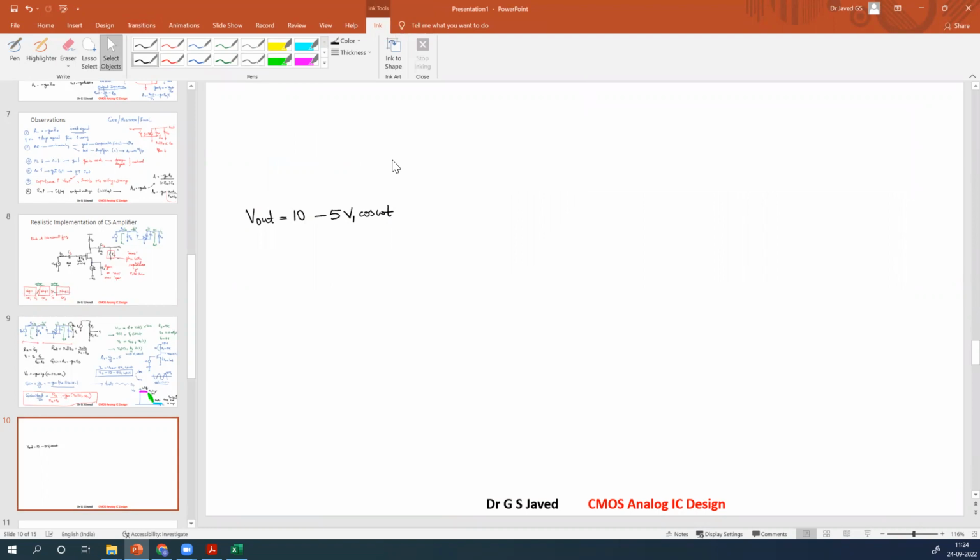The secret is, what is VGS minus VT? VGS has DC volt 4. VT is 2. So what is left over? 2 volt. This confirms that VGS is greater than VT, so the device is on. It is not in cutoff.